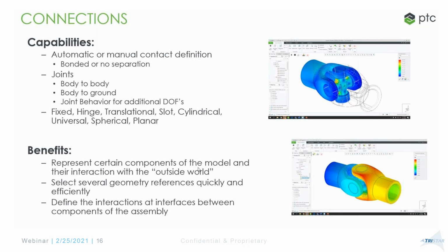You want to have a specific degree of freedom between these components. So typically it's done using interface definitions in most software. For some of you who may have used Creo Simulate, we could use rigid links, weighted links, and some spring elements to create a specific behavior between multiple components.